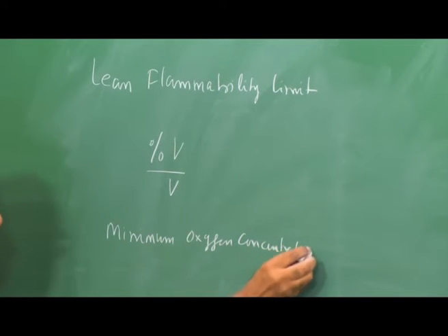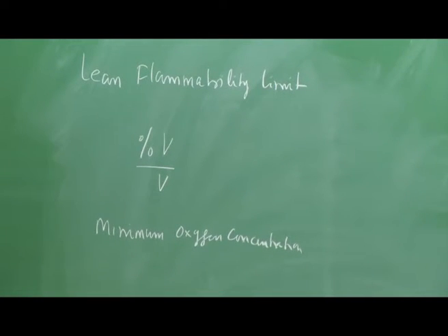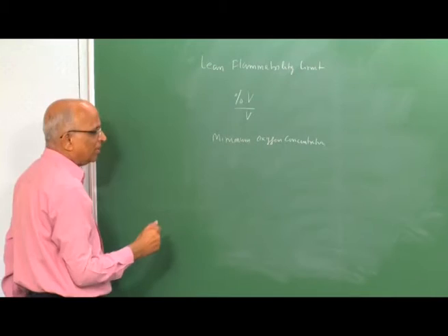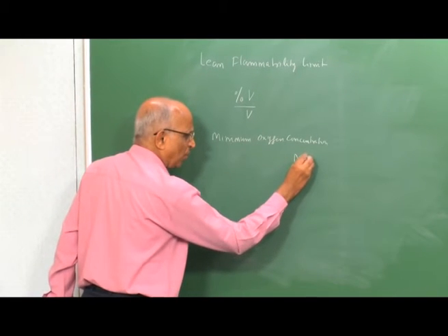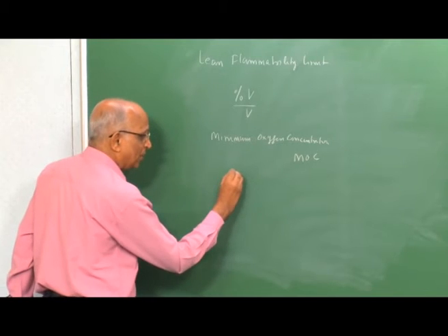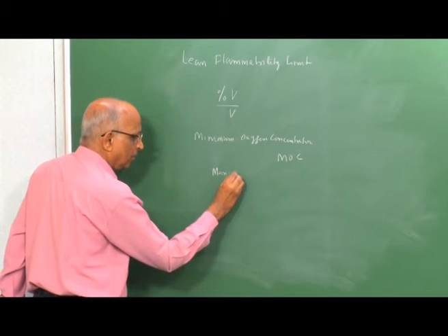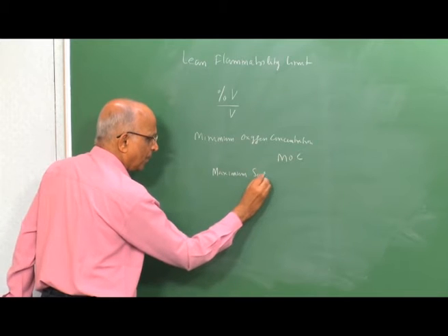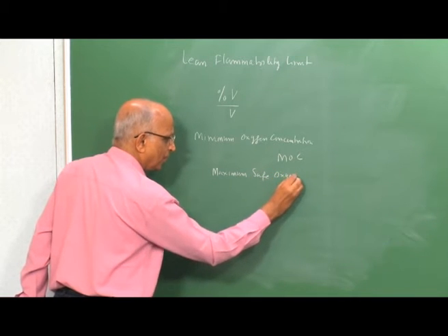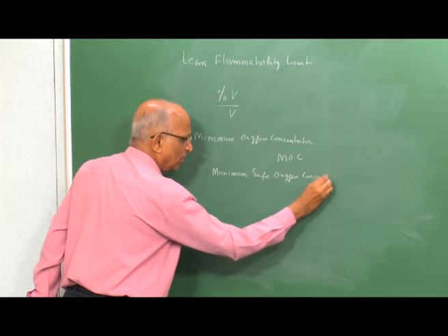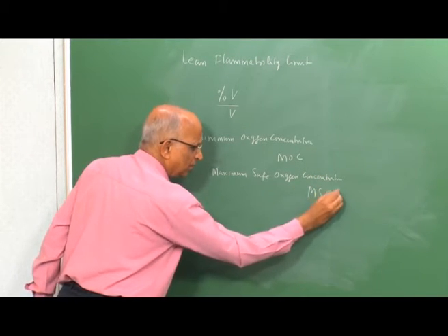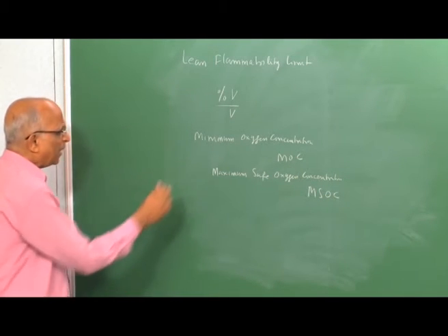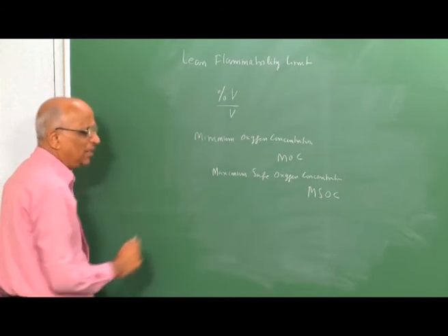And this is a good tool. That means I have to dilute the mixture such that a flammable mixture is not formed. Therefore, this minimum oxygen concentration, spoken of as MOC, also referred to as maximum safe oxygen concentration, that is MSOC, both refer to the same thing, and can also be used to quantify a lean limit.